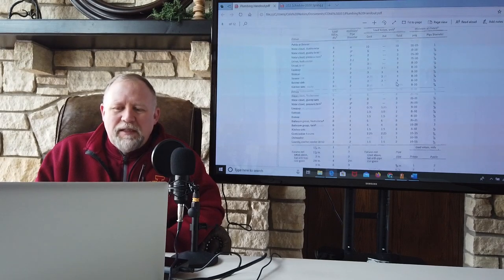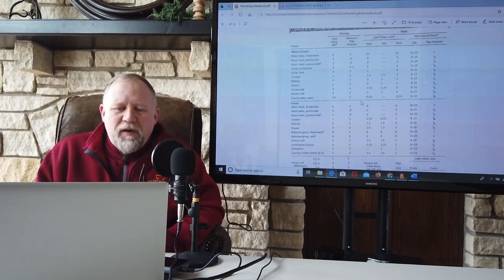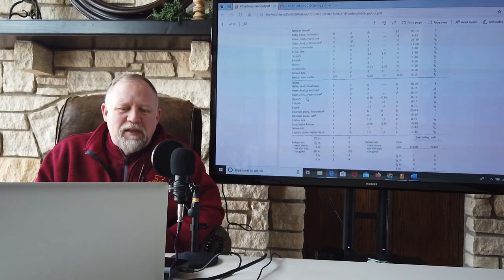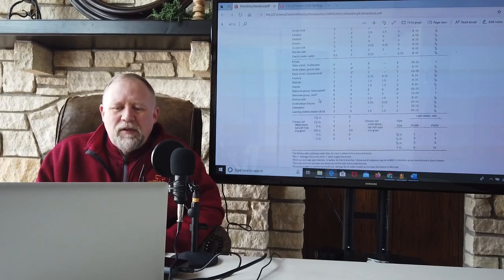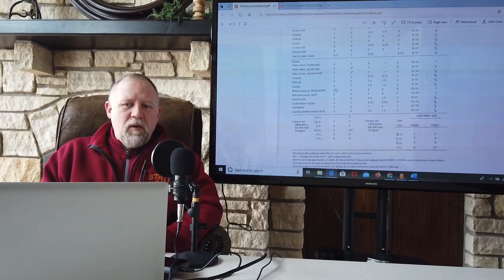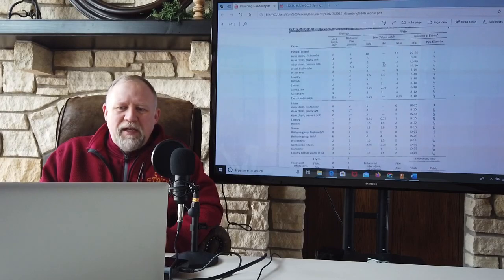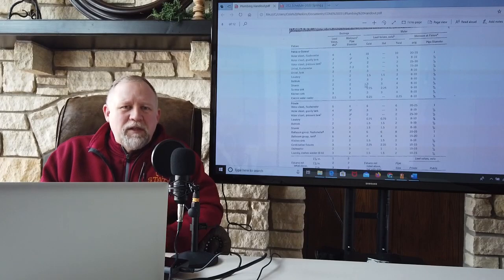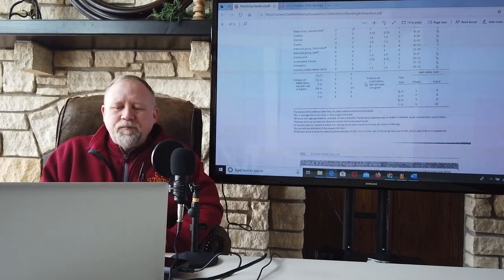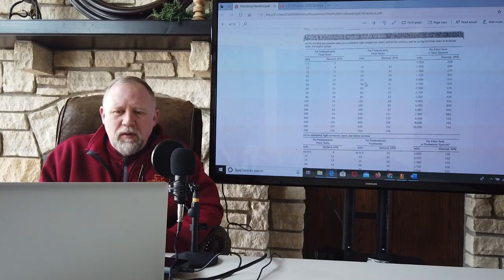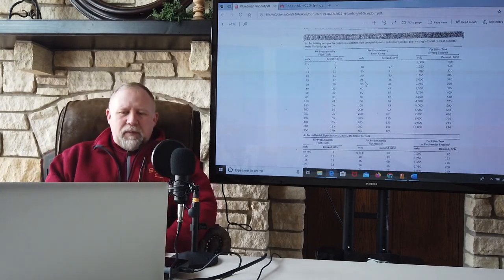So only use the total values when we're sizing the main for the building and then individual bathroom group sizes. All right, also don't forget, only use the public or general top half of this page instead of the bottom, which is private. Don't use that side of the page. All right. So we get the total number of water closets and lavatories and sinks and everything else. And then we multiply that by the total number of water supply fixture units. And once we add all that good stuff up, we're going to go down to table 8.3.